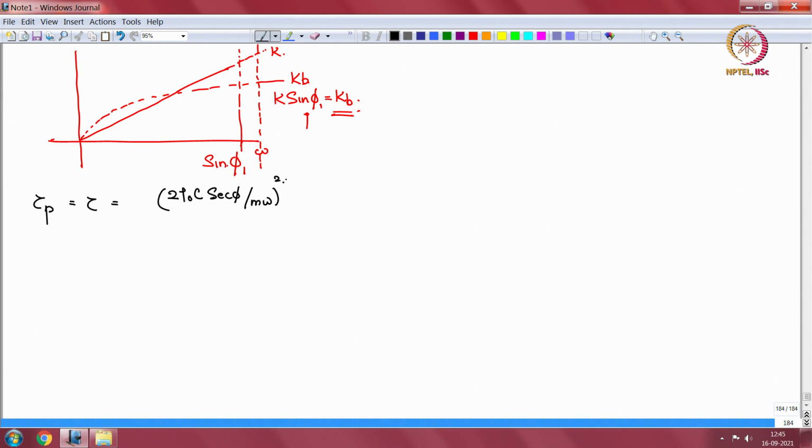By the same accord, if I am at such a frequency that I am just barely at coincidence, then phi 1 has to be 90 degrees. There is no other choice. And if I fall below this basic coincidence frequency, then I have no coincidence possible.